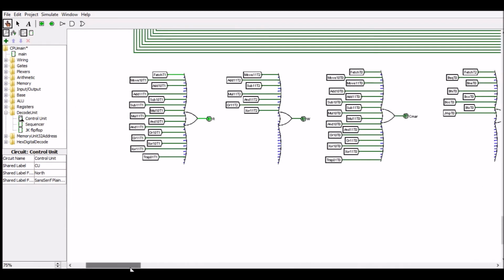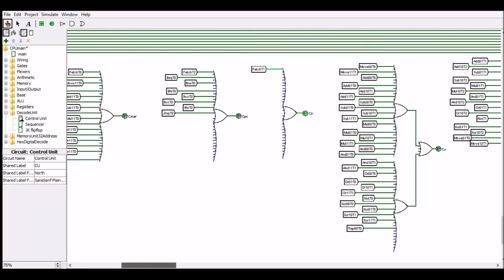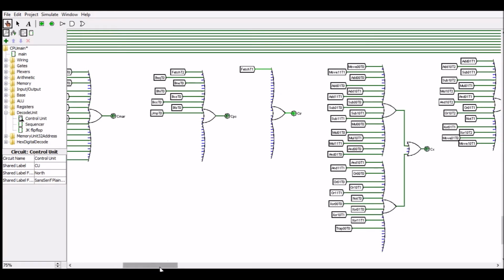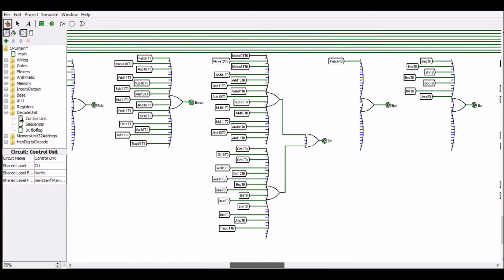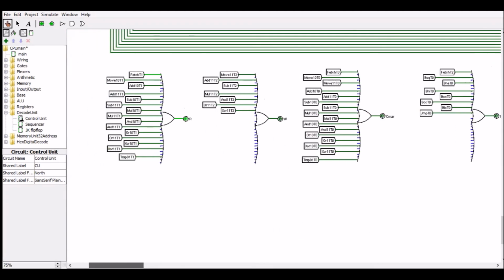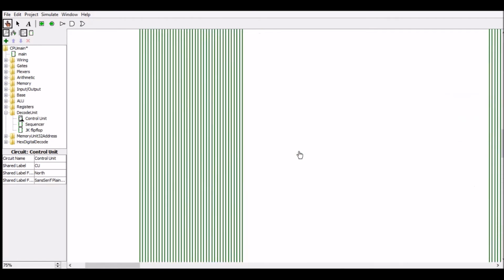So if we have a look along here, fetch T0 is input into this OR gate, and this clock MAR will be output into the main circuit and will clock the MAR. And these gates will be set at the appropriate times, as you can see by these tunnel labels. And there is one OR gate for every tri-state gate or selector bit in the circuit.